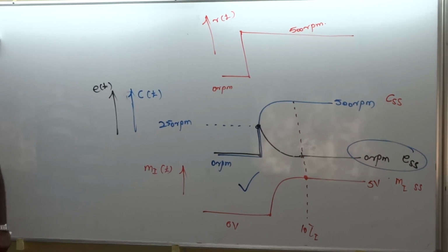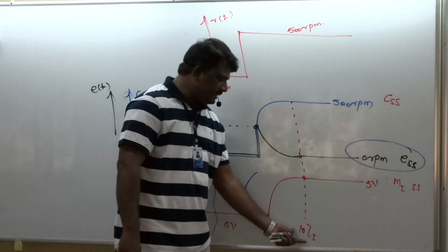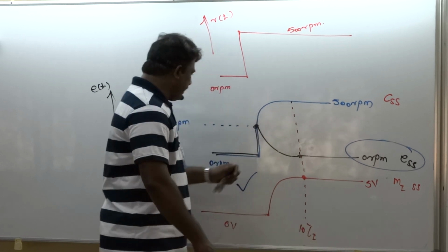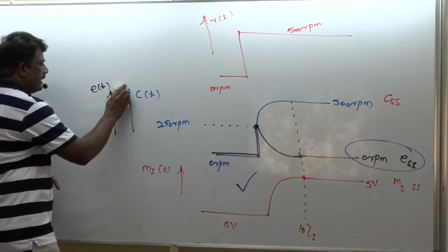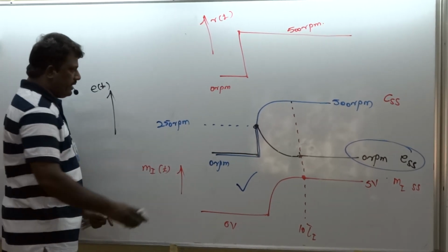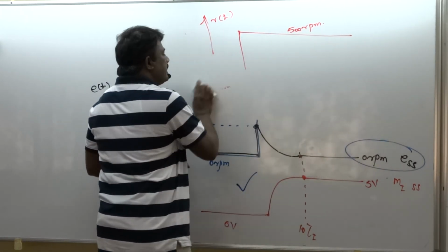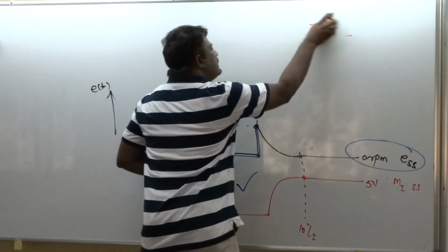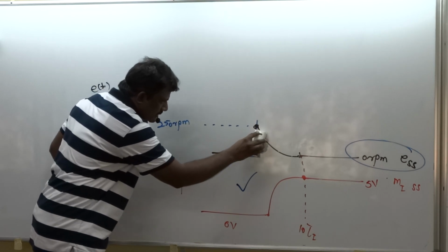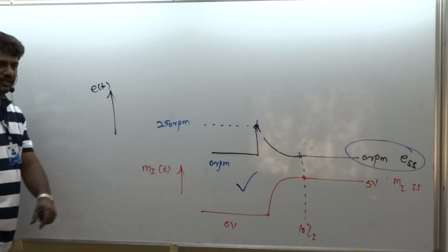So we plot two more signals. Okay? And so far I have given the significance of tau I, but I didn't play any value of tau I. Let us play some values of tau I and see. Now we are going to play with only two signals. One is the error signal and the other, for the given error signal, is what? Mi of t. We focus on only these two. Error response and correspondingly the integral control action response. Okay? This is your error plot, and this is the output coming from integral control action.